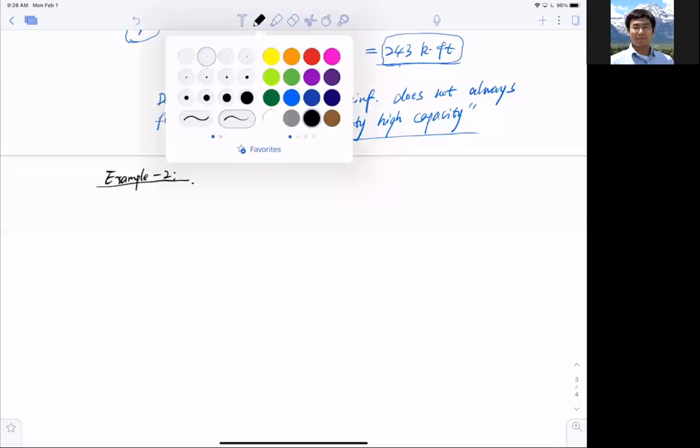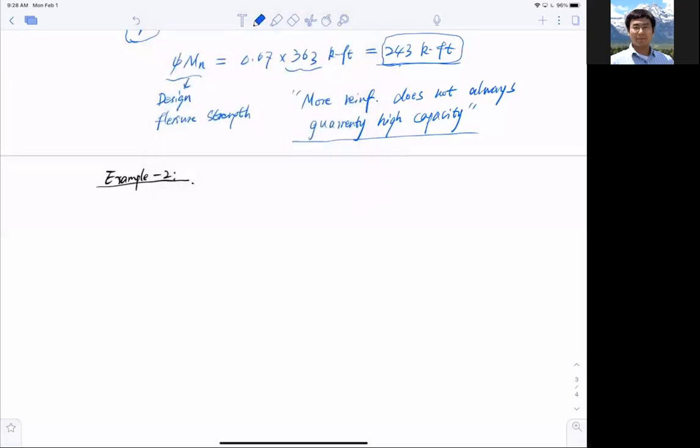And for this section, things are similar, but let me draw that out. I have a width of the section, which is 12 inches again. And the height of it, let me increase that, because of a mistake I made earlier, which is 24 inches. And I am going to simplify my rebar configuration, just say 4 number 9 bars, 4 number 9 bars.